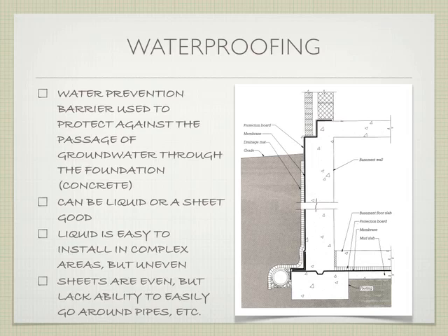Okay, so this is bringing up what you were just talking about. That's good. I'm glad you were there. This drainage mat by itself isn't enough to get rid of the water. Concrete has some porosity to it. It will allow water to come through it. If that's the case, we need to do something where we're actually going to waterproof or create a waterproof membrane between that mat and the concrete to not allow the water to come through. Okay? There's two different types that we can use.